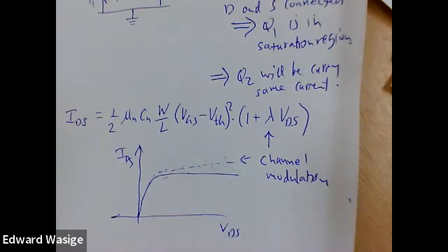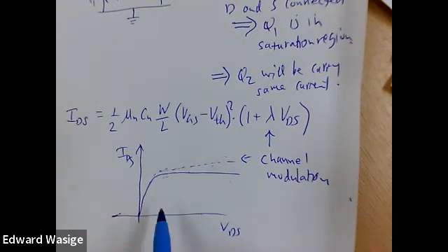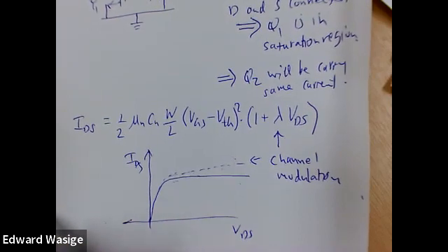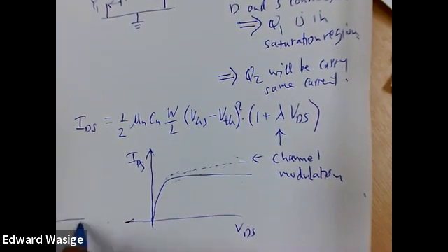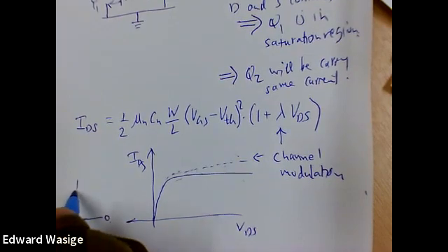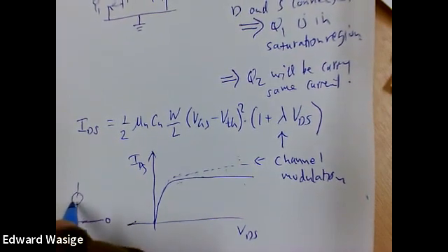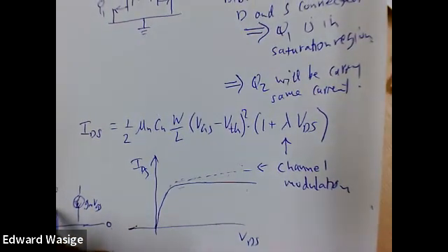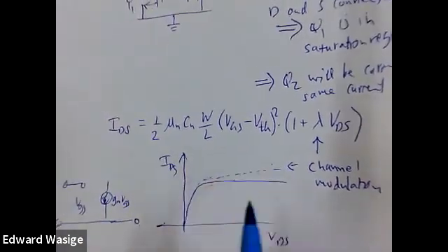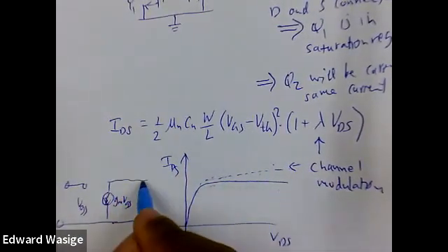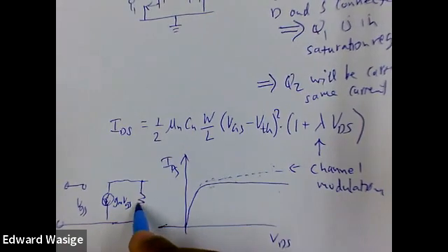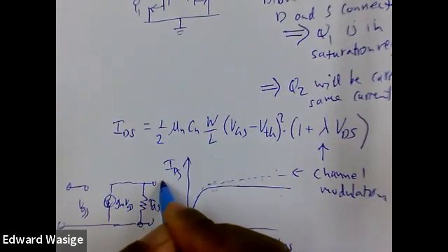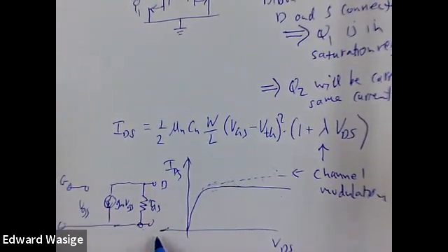Yeah, please find out the details about that. So when we draw the small signal equivalent circuit of this, also just in answer to a question, we'll have gm·vgs, that's vgs. And at the output, we'll have the output resistance, rds. This is D, this is G, S, S.